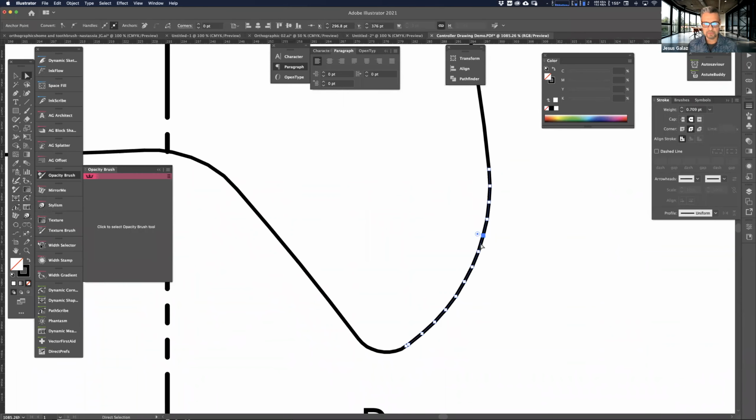So you can see that a curved line is made up of a lot of little straight lines. And that's just the way it represents it. It's not like the perfect path, right? Like here, we're used to maybe an illustrator doing something like this, where these anchor points or these anchor point handles can describe a curved line. And I just have 2 anchor points, and based on these handles, I get this nice curve. But in SolidWorks, you don't get that. You just get a series of these straight lines.